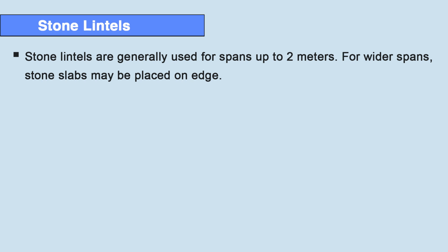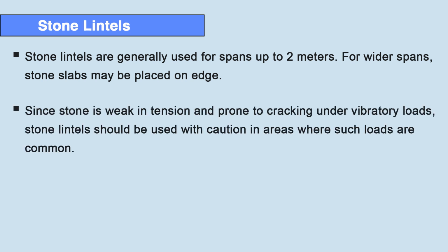For wider spans, a stone slab may be placed on edge. Since stone is weak in tension and prone to cracking under vibratory load, stone lintels should be used with caution in areas where such loads, meaning vibratory kinds of loads, are common.